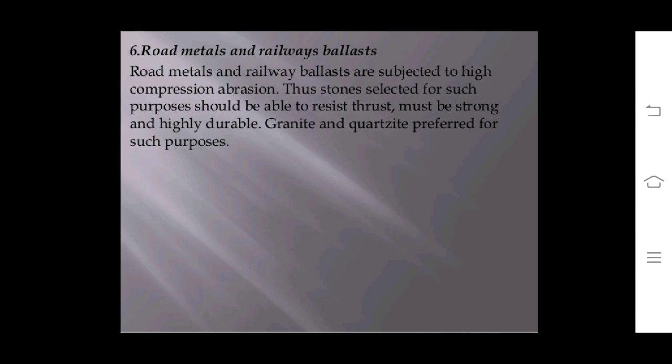For road metals and railway ballasts: road metals and railway ballasts are subjected to high compression, abrasion, and impact loads. Thus, stones selected for such purposes should be able to resist this, and must be strong and highly durable. Granite and quartzite are preferred for such purposes.